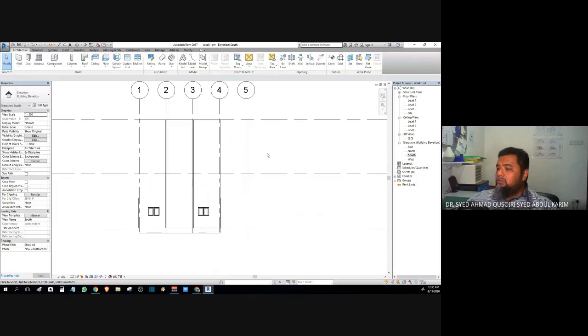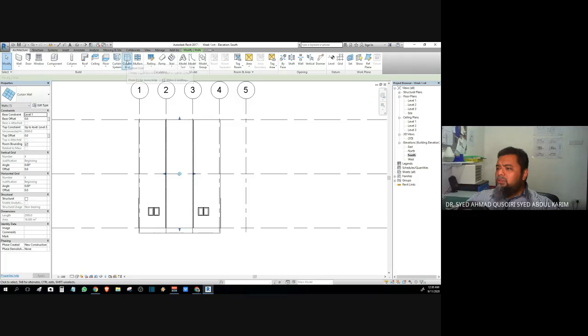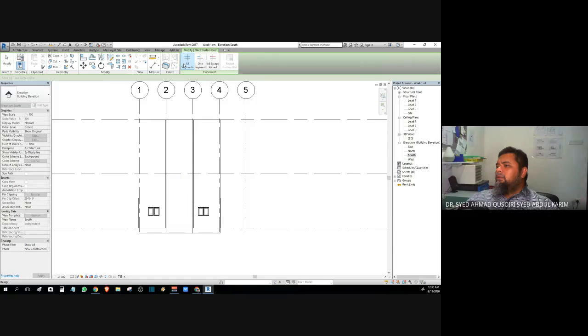So if we want to start to draw, select that place. One way we can draw is by going to architecture and then pressing the curtain grid, and then we will choose all segments, meaning that we will draw the grid through all the segments that are there. Okay, so since we haven't started yet, there's no segment to draw across the panel anyways. So for me, I'll take the center.